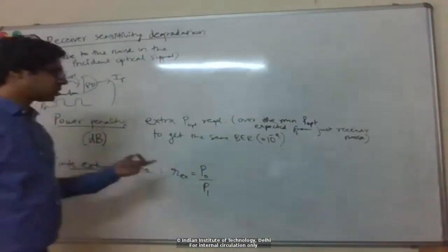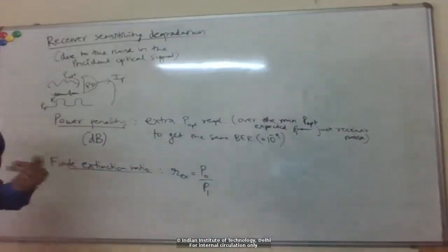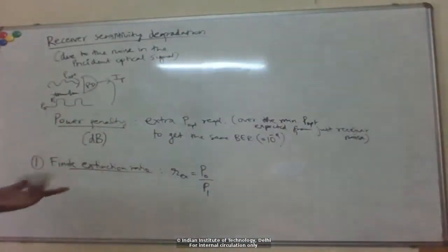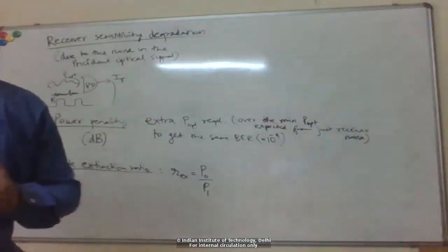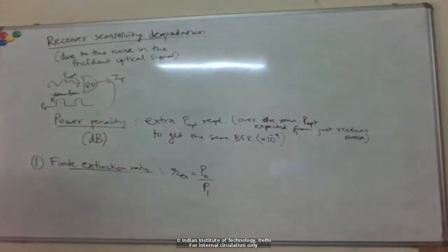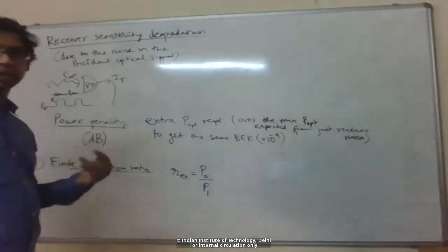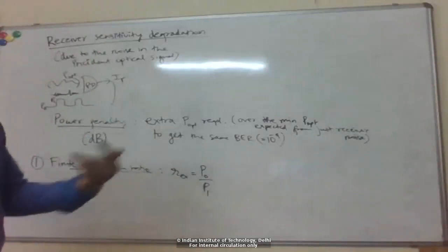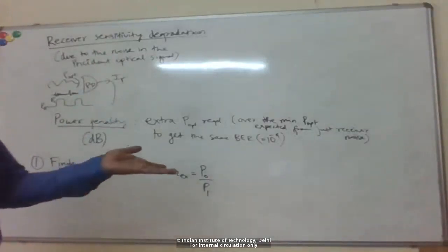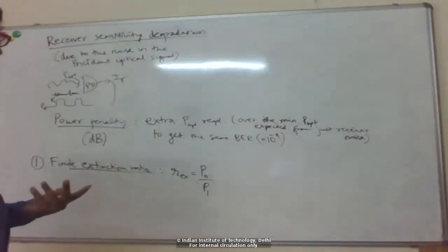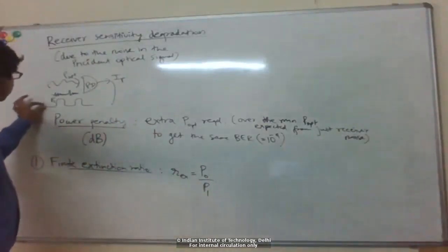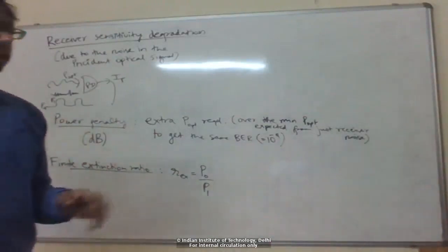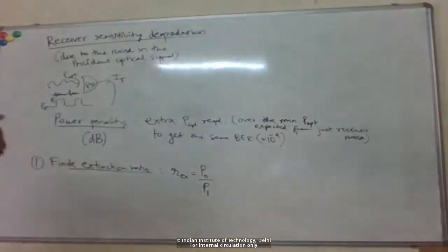But there could be many factors because of which P0 is not exactly 0. One is, again, just intensity noise from the laser. Even if I am turning it off, there is maybe some small power coming out. For example, when you turn off the laser below threshold, it's not completely off. Spontaneous emission is still on, and there is some LED-like emission going on, so that will be some finite P0. Then I'm going through amplifiers.